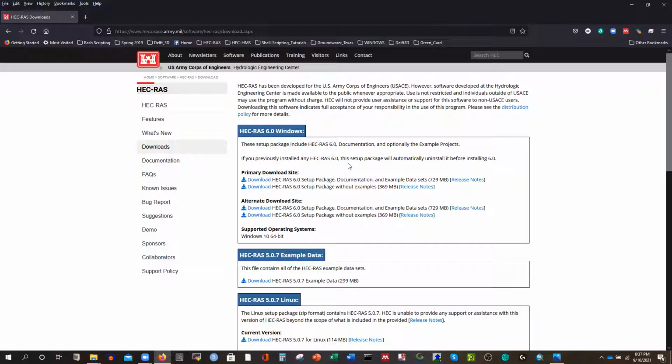So for designing any bridge, we have to make sure what the class of the navigation is. If we make sure, okay, we have a class 1 navigation route, then for a class 1 navigation route, we have minimum vertical clearance, right? And we also have horizontal clearance.